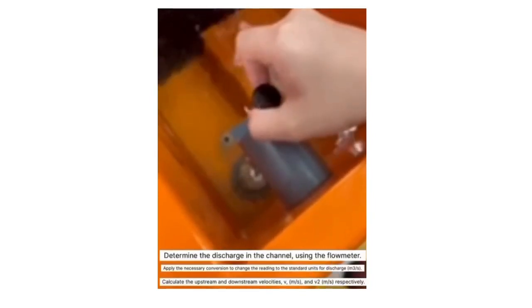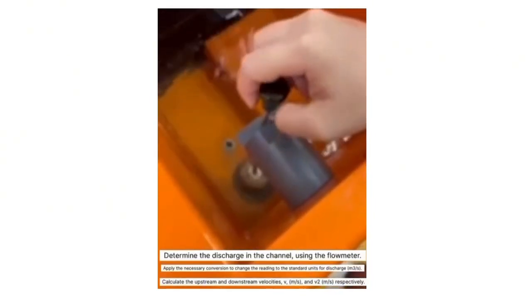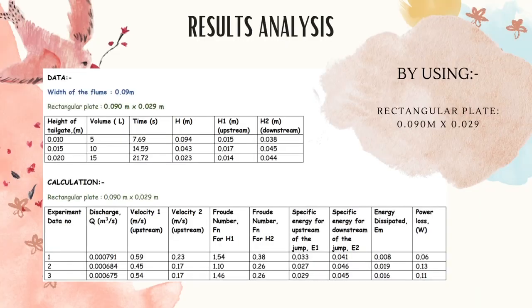Determine the discharge in the channel using the flow meter. Apply the necessary conversion to change the reading to the standard units for discharge in meter cube per second, and calculate the upstream and downstream velocities V1 and V2 in meter per second respectively. Repeat steps 4 to 10 to get 3 different values of flow rate by using different rectangular plates.